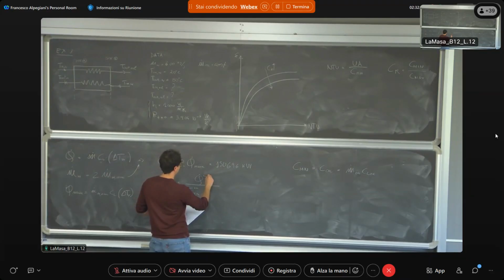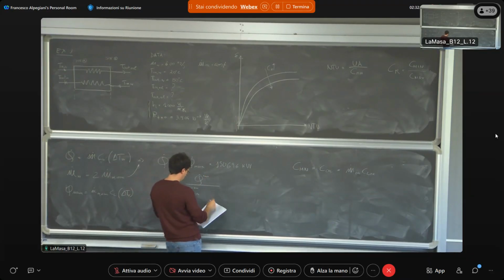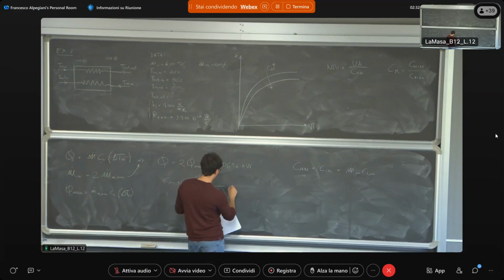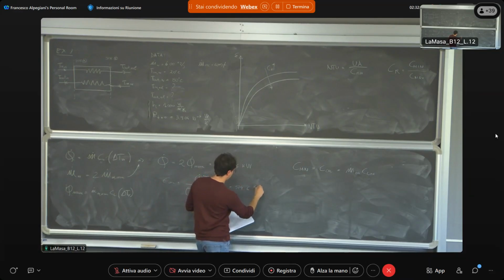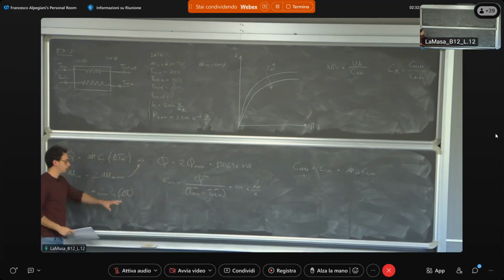Obviously here you have to use the nominal condition: T in oil at nominal condition minus T out oil at nominal condition, and this comes equal to 579.6 kilowatt over Kelvin. It's clear why we evaluated C oil thanks to the nominal condition.